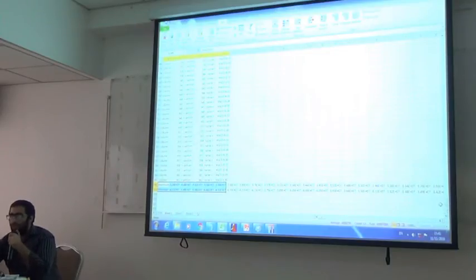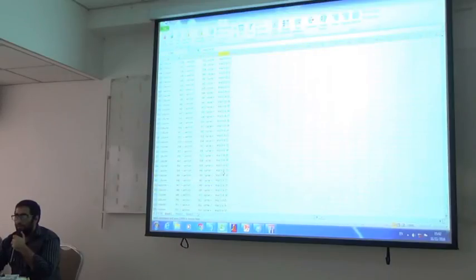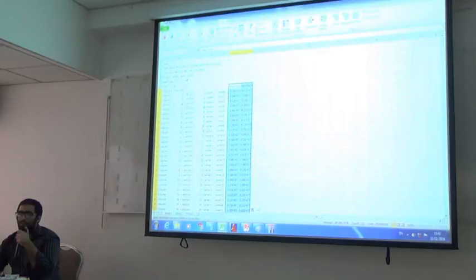So how do we do it? If you want to select the data like that, you can use Control Shift and then the right arrow. Okay, and then you can just copy it. After you copy it, we go back to where the data is, and then from there we go at the top, right? And then select this cell, the cell above level 1, right click on it and then use this option of transpose. Right, if you select the transpose option, you will see that all of the forces are already here.